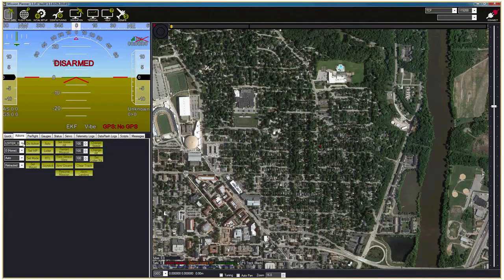So if you are flying manually and you say, oh, I kind of want to look at that, you can click Loiter Unlimited and say Do Action. It'll start loitering there, and it'll just keep circling until you tell it to do something else. You can set modes in this tab, in this drop down. RTL is return to launch.